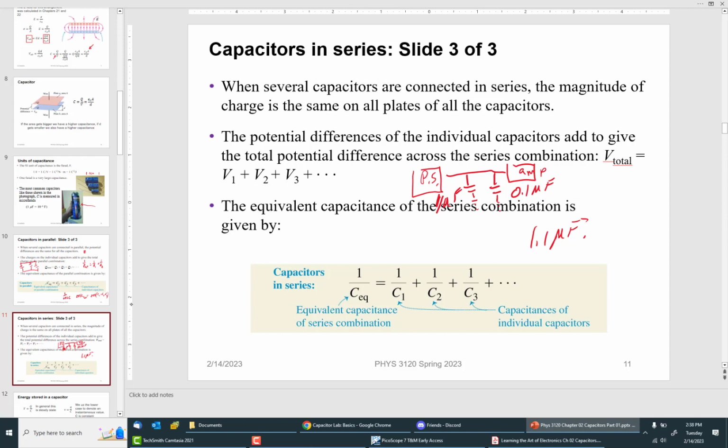We're not going to go to this level of nuance until we start wiring up our little chips, and then we'll start putting in what are called decoupling capacitors. If you have a very sensitive circuit, it could be that the little bit of ripple will screw it up. So you have these caps.